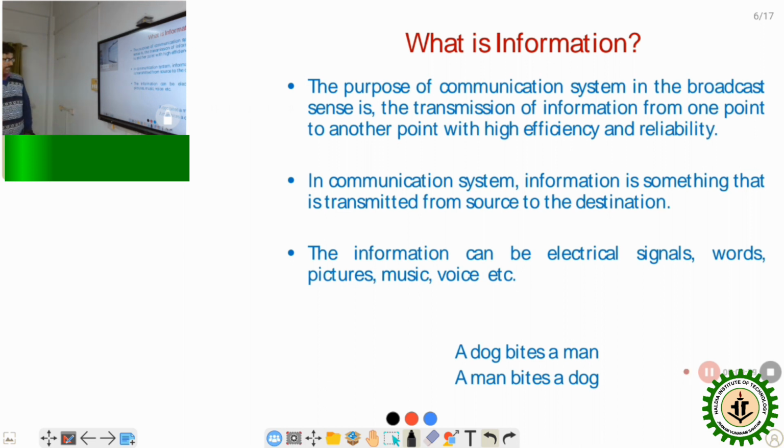In the second sentence the probability is very low, so all the readers will read this article. From these two sentences we have seen that where the probability is higher, the chance of getting information is very low, and where the probability is lower, the information gained is much higher. So information is inversely proportional to the probability of occurrence.